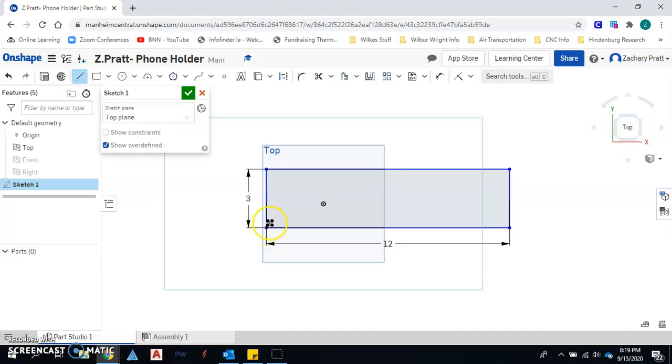And this is where we'll consider this to be the front side of our phone holder project here, the template. So make sure you have your template out in the same position as the way you're drawing here. And we want this line to extend beyond the top edge of our rectangle, and this is just so we can easily click on that. And again, you just hit escape, and that'll exit the line tool option.